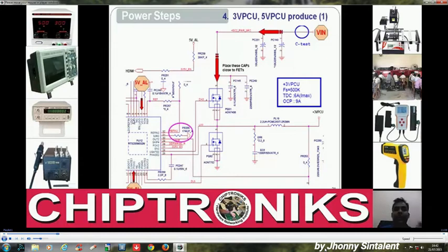So if your LDO is coming, it must go inside VCC and PVCC. These are connected, okay? These are very important. VCC is for the internal logic of this regulator IC, whereas PVCC supplies power to the gate drive circuit which generates LGATE2.